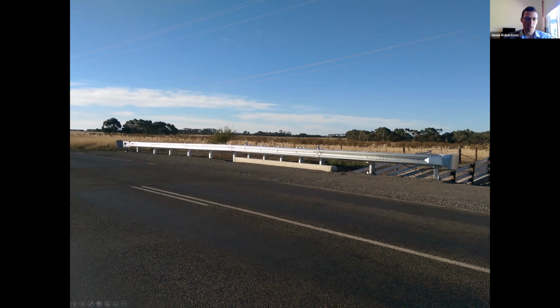So the desirable thing to do here would have been to design that barrier to provide an appropriate length of need on this side and on this side. Given that we've forgotten about clear zones, we'd provide the same length on this side and a terminal of a type that can withstand an end-on impact. So this is a bare minimum installation. And unfortunately, you do see a lot of this where a token length of barrier is installed.